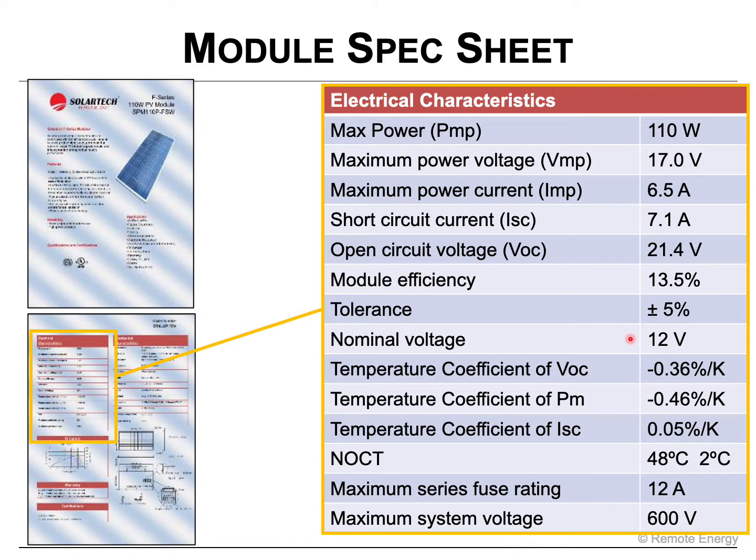so that we would push the electrons to the battery. It's giving us temperature coefficients. We're not going to get too detailed into this in this presentation, but this is how it's telling us how our electrical parameters or characteristics are going to react with changing temperatures. And so that's why there are different numbers for the VOC, for the power, or for the short circuit current. And then we're really not going to be talking about the rest of this for this presentation, but the spec sheets always give you a lot of information.